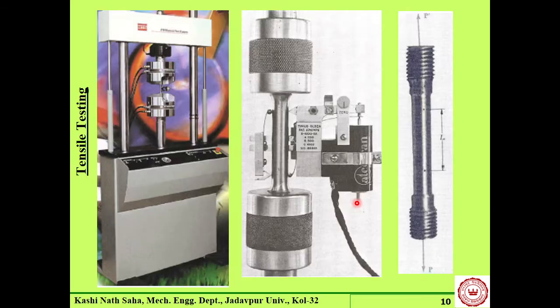So now what do we need to measure from here? The distance between those two fixed points. You see there is some arrangement by which the distance between these 2 points is noted. That mechanism is known as an extensometer in general. There are different types of extensometer. Again, we are not going to discuss that. And the other part is the measurement of load.